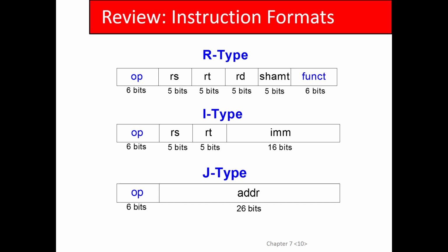The instruction has fields, each of which is just connected to a different module inside your CPU. The 3 register fields are simply connected directly to the address bits of a RAM, which forms the register file. The RAM is 32 deep, 32 rows, right? So log base 2 of 32 is 5, and that's why they're 5 bits each.